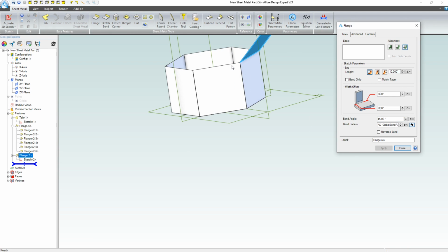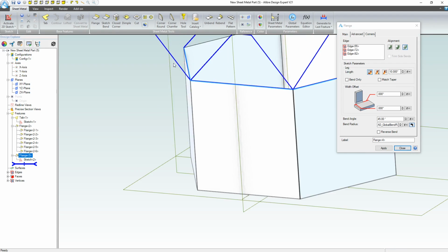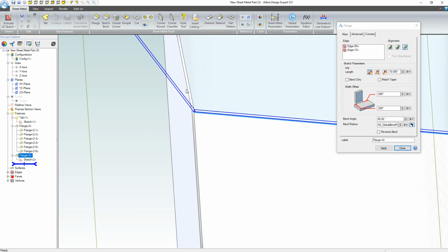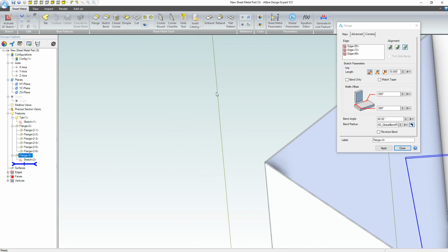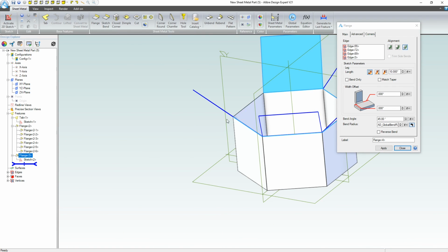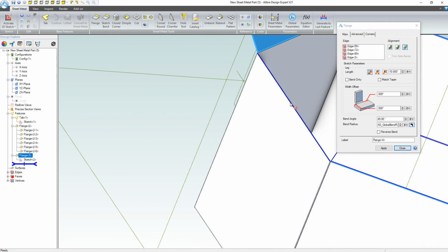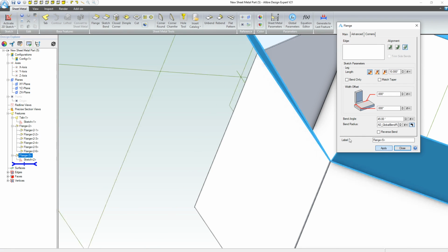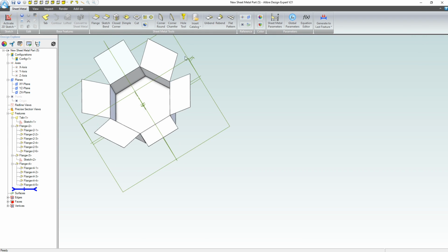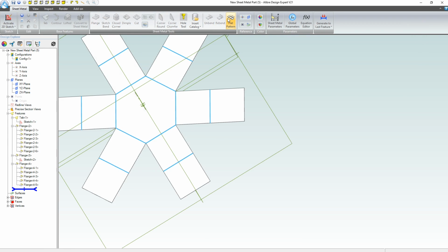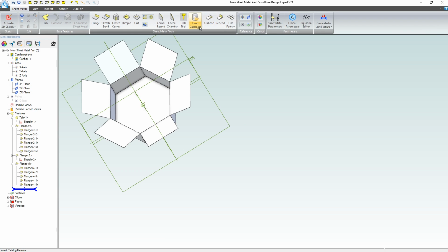so I can almost make this, you know, hexagon, almost like flower petal type of shape. Here I've selected the wrong edge, and it's gone in a way that I don't wish to go. So there's an interesting little sheet metal aspect that I think is pretty cool, right? So we'll close that, and as always we can extract our flat pattern.